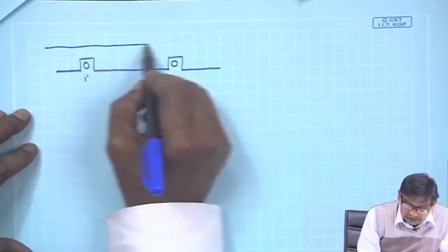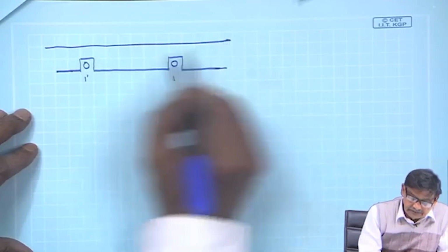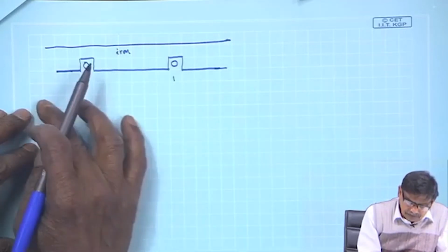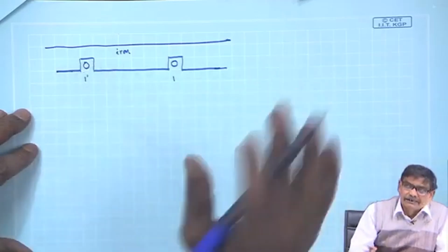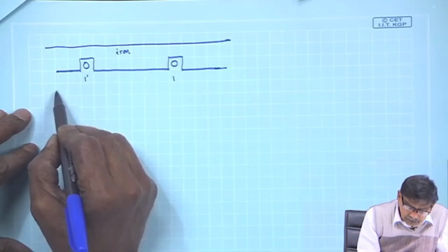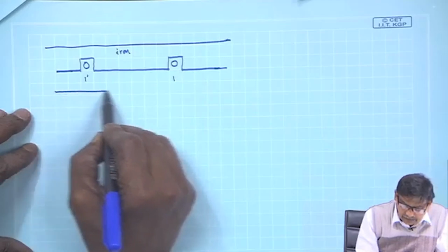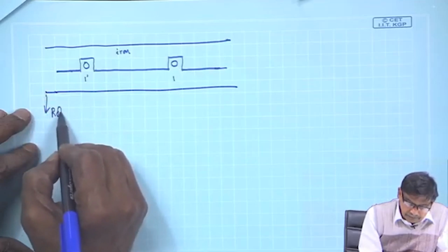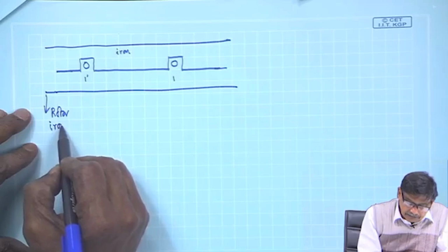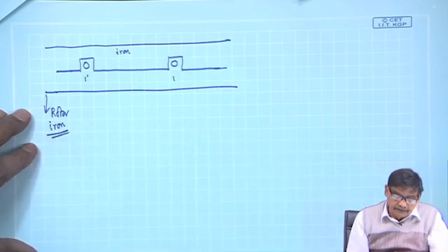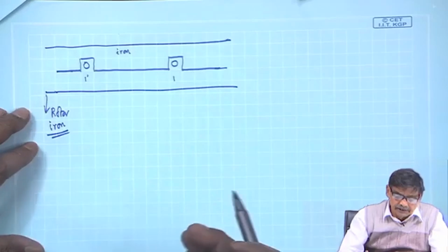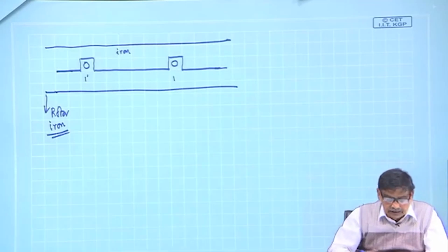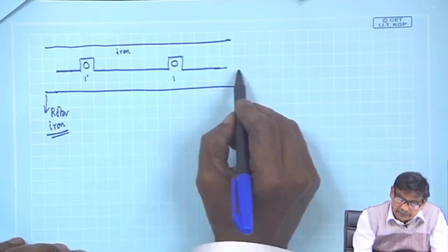This is the outer stator rim circumference, this is all iron, and on the rotor I have not assumed any coils. There may be coils, but they are de-energized. I am showing the air gap at a larger scale, though it is much smaller. Below this is the rotor iron. The developed diagram view is this, and the mu r of rotor iron and stator iron are very high compared to the air gap, and this is your air gap.